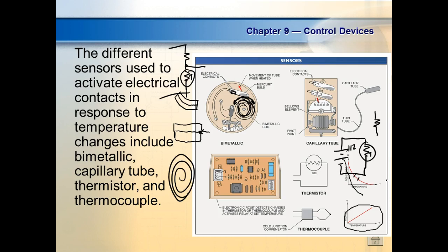Well, not really calibrated, it's just set from zero. So if I came over here and did this at some degrees, 32 degrees, or let's do centigrade, so 0 degrees, this guy right here might have 2.5 volts out. Well, I would like it to have what? I would like it to have 0 out, right? You understand? So now it means something.